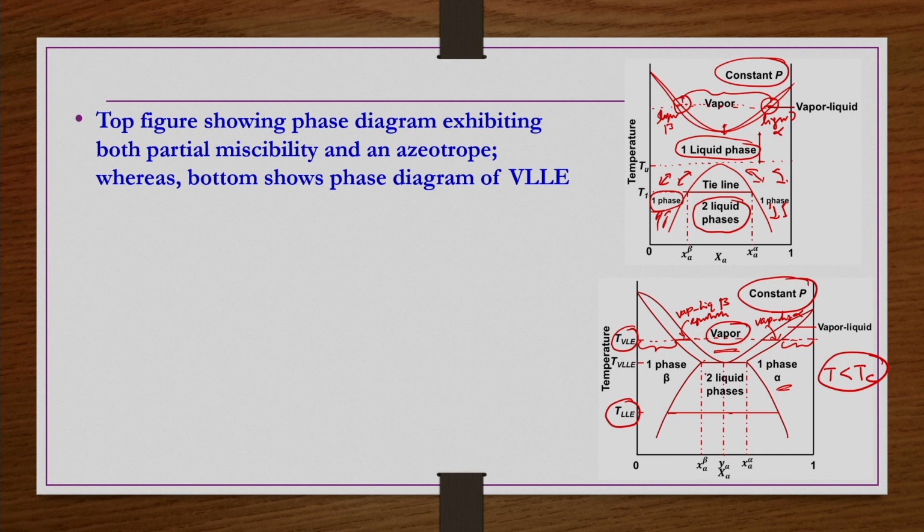But at this temperature, at VLLE, we call it VLLE because here this VLE and then LLE curves are intersecting, and then we have a kind of line. Not necessarily will there be a line, there may be more complicated things also possible. So, at this temperature, the two liquid phases are coexisting because this envelope includes the region of LLE.